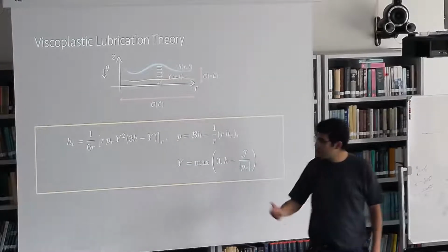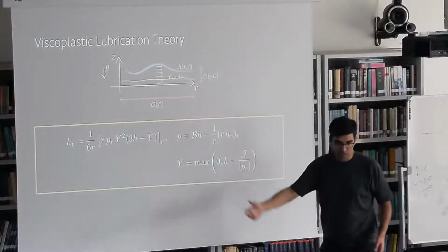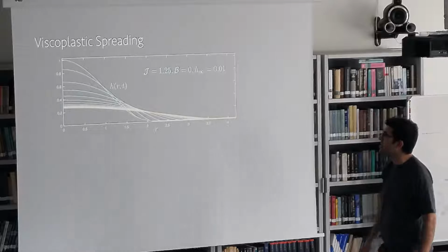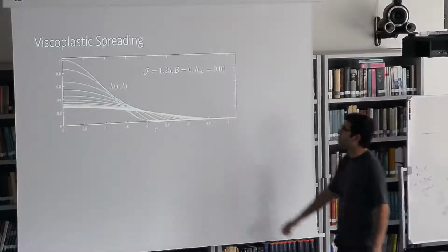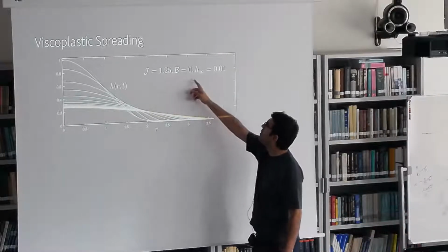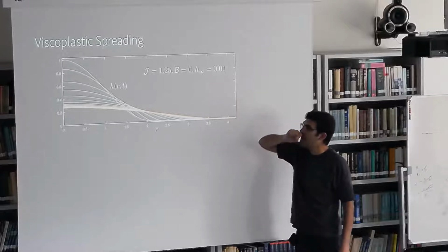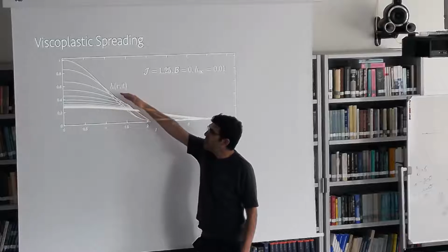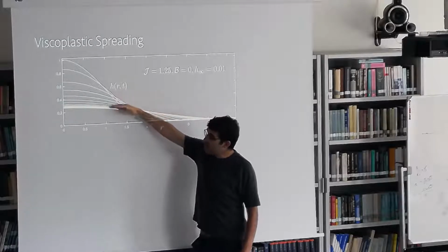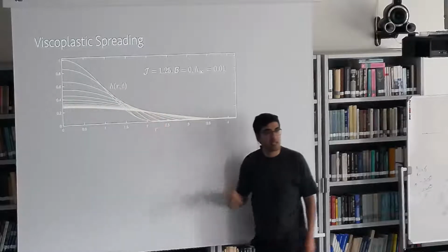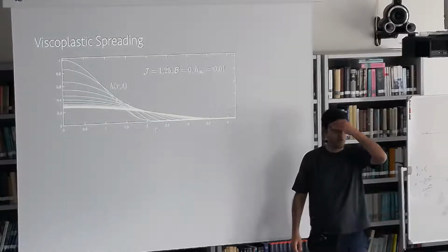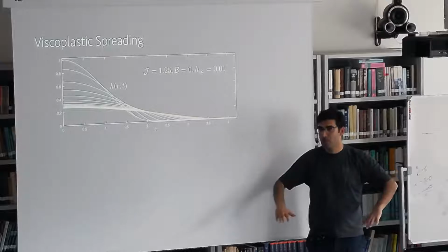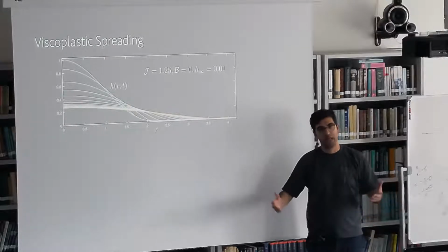Okay, so I can solve these equations, which we did with the finite difference method. And here's an example of solutions for a given plastocapillary number, Bond number, and thickness of the pre-wetted film. So this is the initial condition. I let it flow, and over time it slows down, but it stops at what I'm showing with the golden line. The golden line is where the stress inside the droplet everywhere is below the yield stress, so it doesn't move anymore. So plasticity dominates.